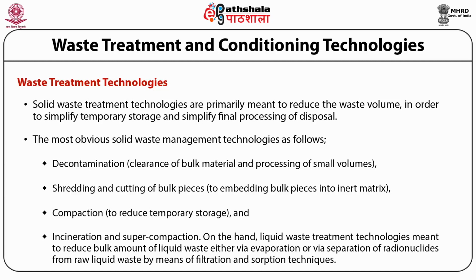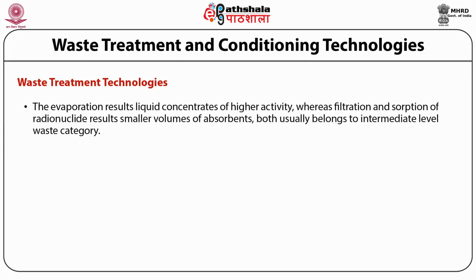On the other hand, liquid waste management or treatment technologies are meant to reduce the bulk amount of liquid waste either via evaporation or via separation of radionuclides from raw liquid waste by means of filtration and sorption techniques. The evaporation results in liquid concentrates of higher activity, whereas filtration and sorption of radionuclides result in a smaller volume of absorbents. Both usually belong to the intermediate level waste category.